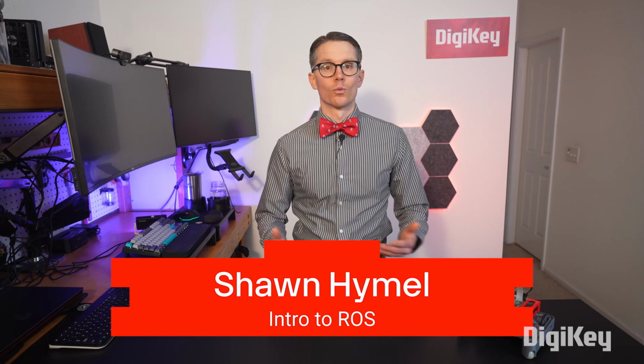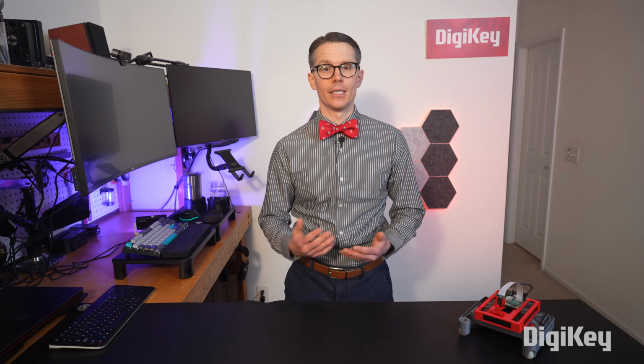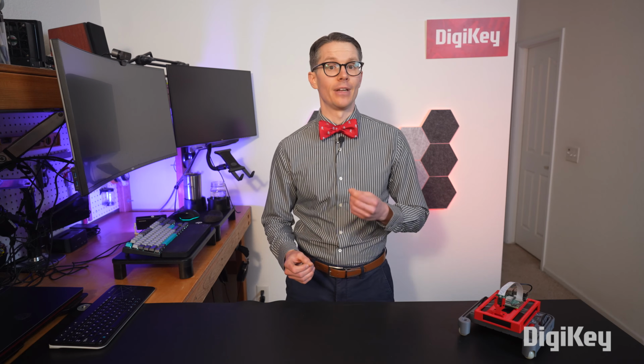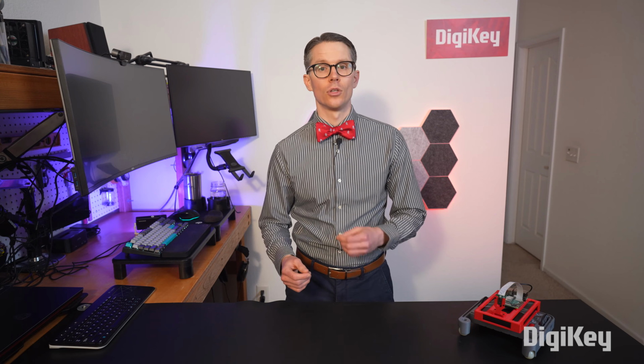We have been writing ROS2 nodes for a few episodes now, and each time we run them manually from the command line. This is fine for testing your nodes and debugging, but it becomes a bit of a pain if you want your robot to start functioning with all nodes running from a single command line call. That's where launch files come in. ROS2 has a straightforward process of creating scripts that launch multiple nodes with given parameters.